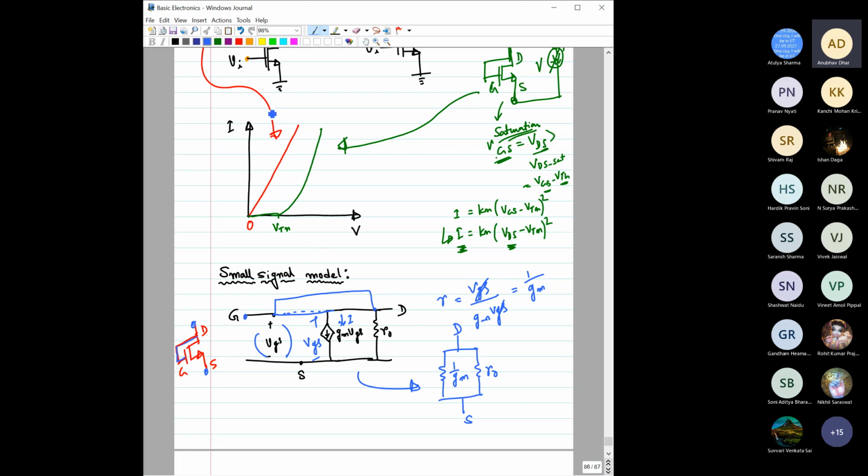So here we are connecting this because of this configuration. You see this gate and drain are connected. Instead I could have connected it here, the same thing, right? Instead of connecting it here, this is the same wire. So this is the voltage VGS, and the same voltage is dropping across here. So for this current source, the supplied current is I and the voltage drop across it is VGS.